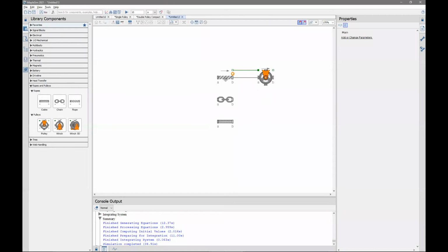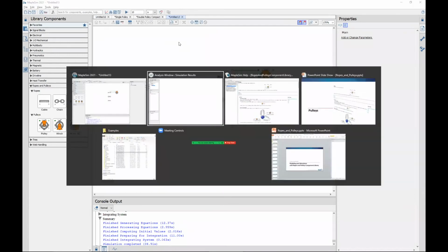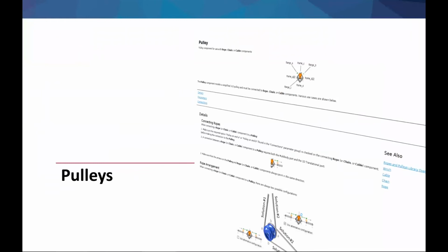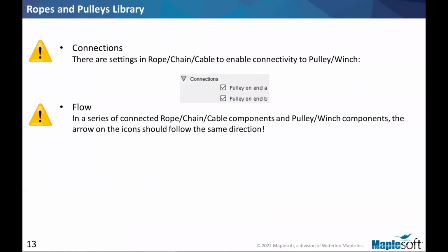And those changes mostly are because we need to find out what is the tangent direction between the starting point and the unknown point at the start of simulation to the surface of the pulley, which is our tangent. So you will see in the examples from this point on that you need to use the options for connection to a pulley before connecting to a pulley, not after. So you select the option, then connect.